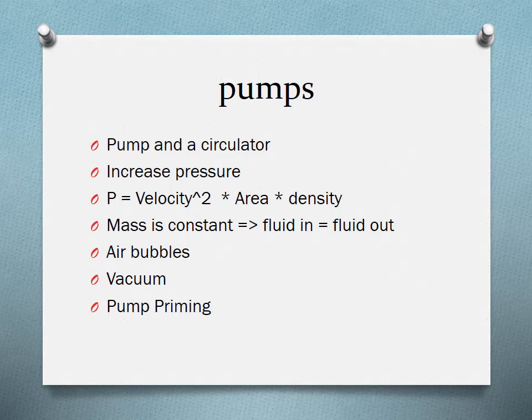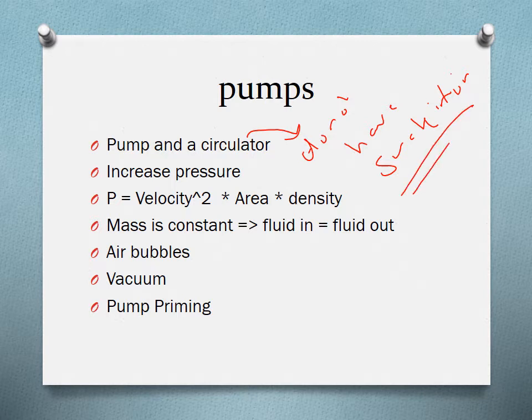So the first thing is, what is the difference between a pump and a circulator? Those terms are used interchangeably. However, from what we know, circulators do not have suction power. There's no suction in a circulator. Pumps have the ability to provide a certain amount of suction. Like a sump pump, it can have more static head. So let's say static head is a main difference here.